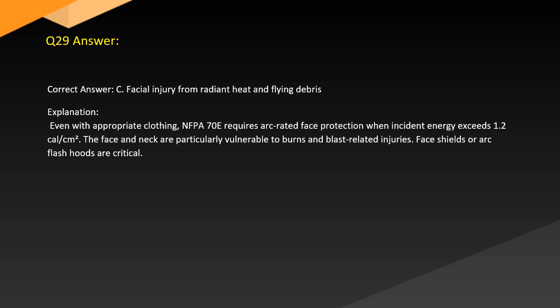Answer. Correct answer: C. Facial injury from radiant heat and flying debris. Explanation. Even with appropriate clothing, NFPA 70E requires arc-rated face protection when incident energy exceeds 1.2 cal/cm². The face and neck are particularly vulnerable to burns and blast-related injuries. Face shields or arc flash hoods are critical.